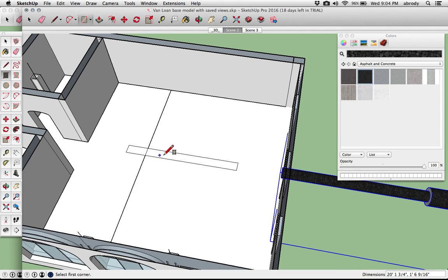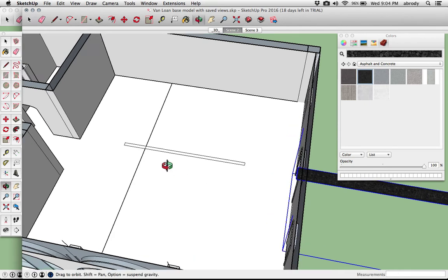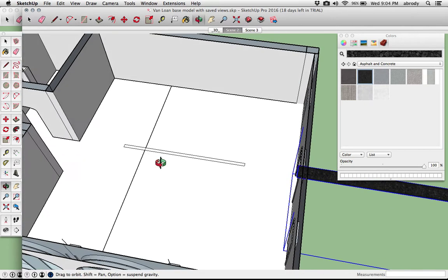If I want that wall to be exactly some dimension, I can actually type it in. Now, I'm not moving and clicking or anything. I just initially drew that rectangle. All I have to do is type in 20 feet, and you do have to use the little single apostrophe, comma, 6 inches. And again, if you want inches, you have to type it. Hit enter, and now I have a wall that's 20 feet by 6 inches.